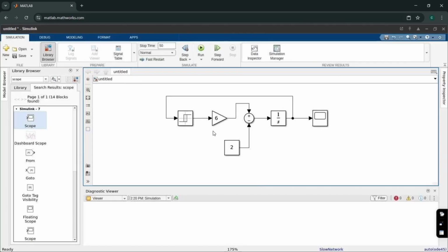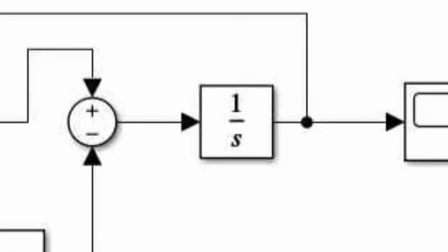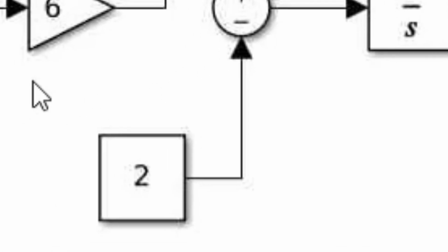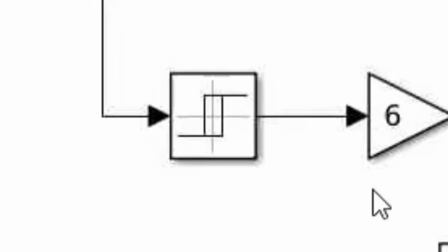The Simulink model is composed of several key components, each representing a part of the real system. The integrator block represents the soil itself, where the moisture level changes over time. The constant blocks are used to define important parameters such as the desired moisture threshold and the drying rate, which simulates natural evaporation of water from the soil.